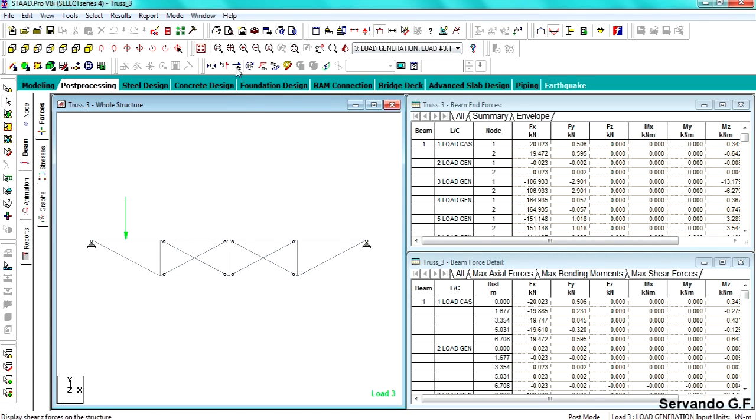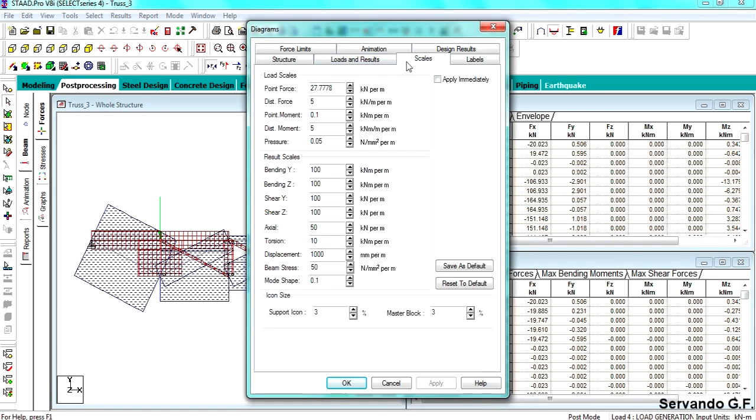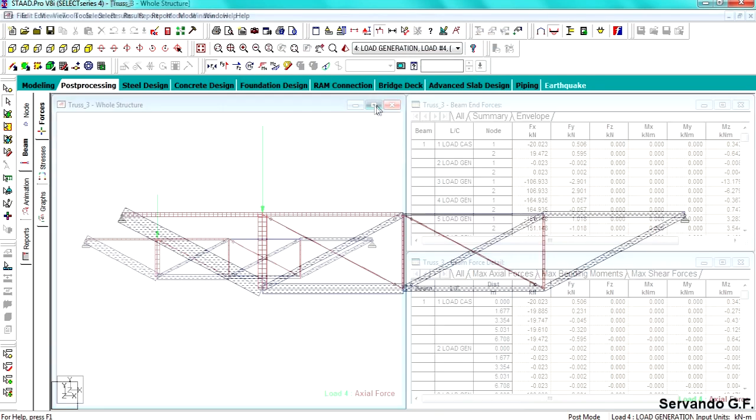And then if I click on the axial forces, axial here, well, this is a little bit messy, but it's useful, because now I'm going to show you that when you get these kind of results that are not to scale, what you can do is go to symbols and labels, scales, you check axial, so if you add that 0 here, you will produce this.